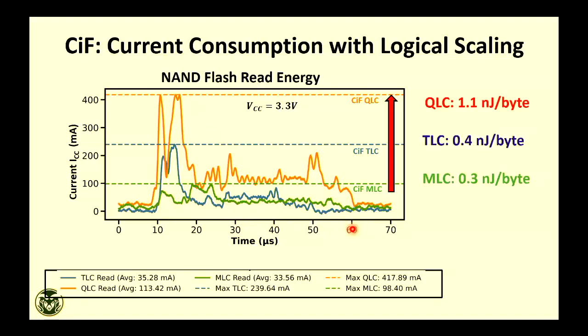So we did this, so we can see as you increase this, MLC, TLC, QLC, you can improve the performance because you are doing more bit operations together in QLC, but at the price of increasing energy, because you have to apply more references to decode. So yes, logical scaling will improve the performance of your bitwise computation, but it will also make it more energy consuming.